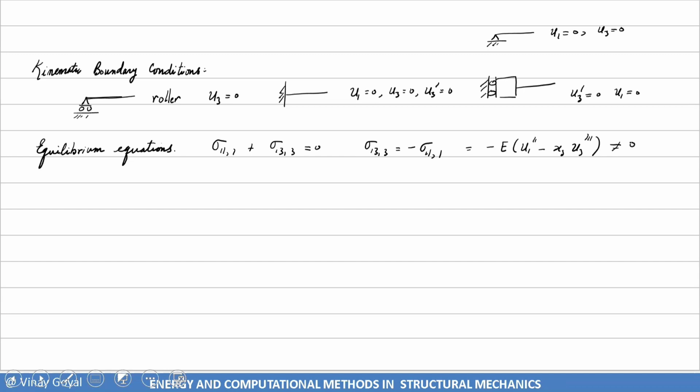However, we had stated earlier that gamma 1,3 is 0, but by Hooke's law, sigma 1,3 equals G gamma 1,3, which is 0. So there's inconsistency between what I get here when I integrate that to get a non-zero value, to this, which says is 0. But that is inconsistent because of the assumptions that we have made.